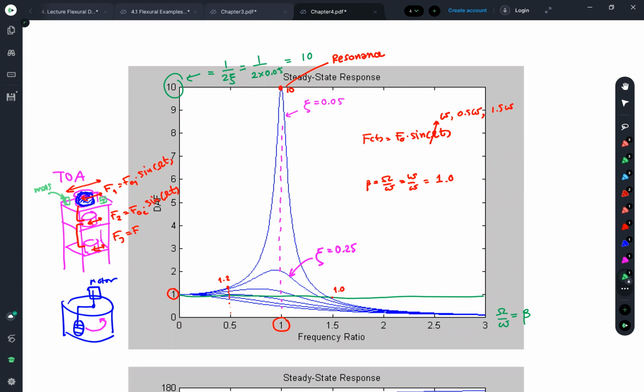Can any one of you tell me how to solve this problem? Very easy. Add the bracing. Yes, you do the bracing? Okay. Yes, one of the ideas is to modify the stiffness to have the higher frequency, I know. You do something like this, right? The steel bracing.